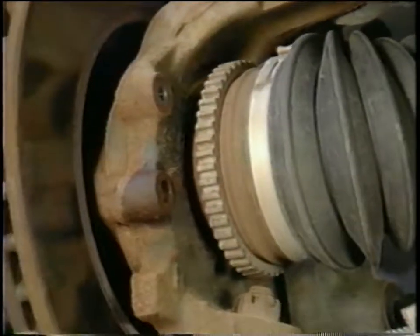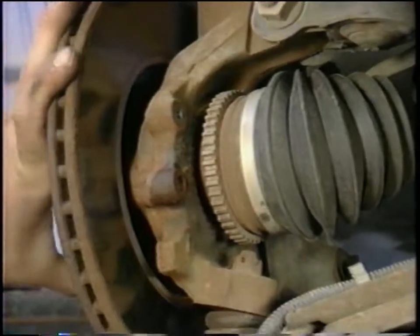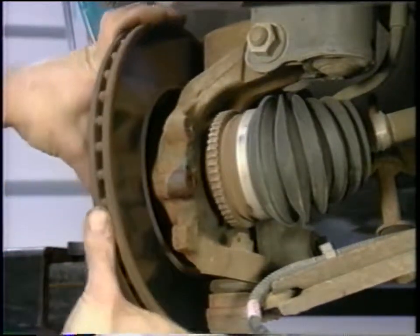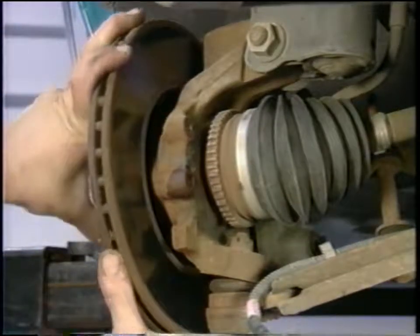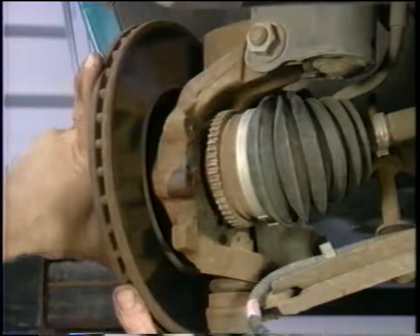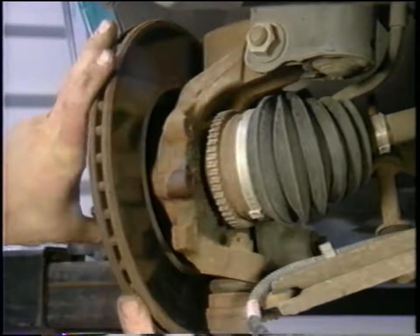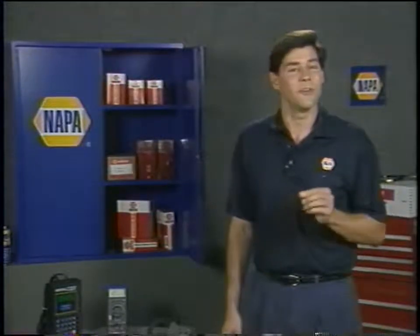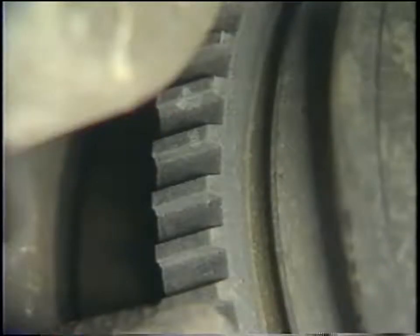To produce an accurate signal, a wheel speed sensor also needs a sensor ring that is in good condition. Broken or damaged teeth will cause the sensor to miss a pulse every time the defective tooth passes under the sensor. Depending on the sensitivity of the ABS control module's self-diagnostics, this may or may not set a fault code. But either way, it will affect the accuracy of the signal.